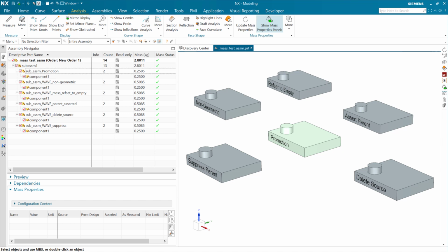And we can't just infer exactly what the user is trying to do with wavelinks, because there's, again, a lot of ways to use them, right? There are, in fact, a number of customer usage scenarios for wavelinks where an automatic offset or subtraction of the original body properties is undesirable, highly undesirable, right? So when customers use wavelinks, we can't read their minds and auto-determine which of these usages they're attempting.